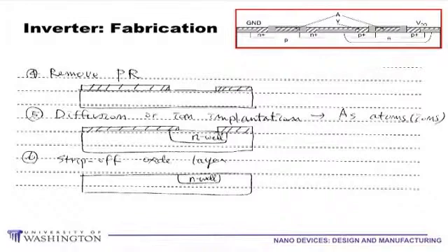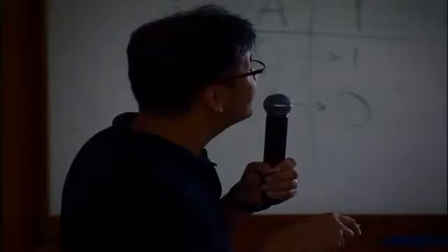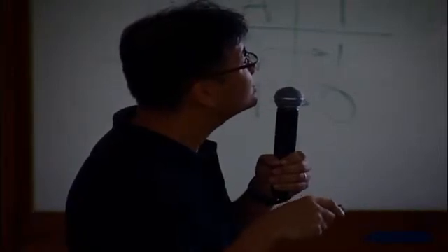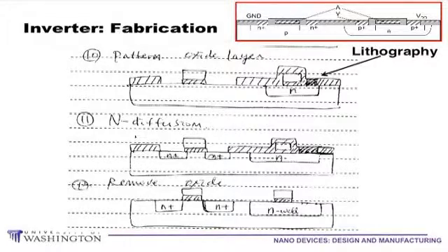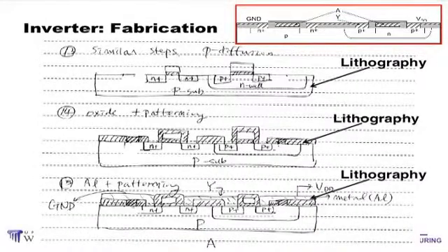So now we use the second step and go to another deposition of an oxide layer. And we need a lithography in here in order to identify the N well on the left side. Okay? So again, the third lithography was done in here in order to create two wells. Then we will diffuse N-type materials in order to create these two N wells out there. So now we are at the stage to have these two N wells and then a large N well here, but we have to create these two P wells out there. Anyway, after this step, we will remove the oxide layer, and we will go through similar steps.